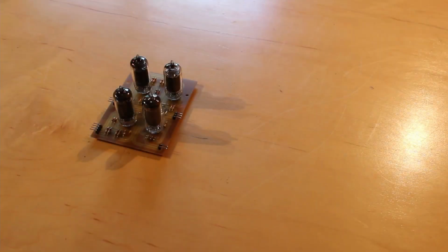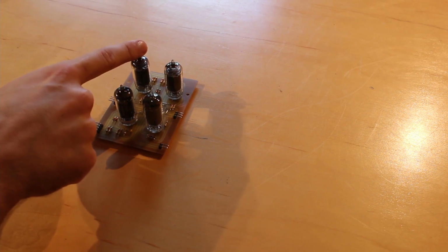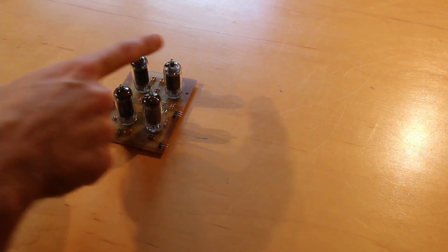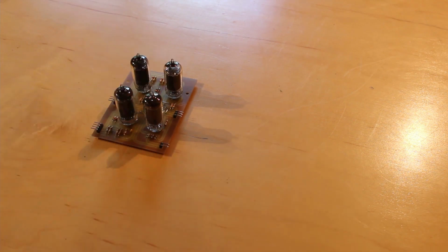Well, this is the board that I want to test out, and it has a NAND gate here for our clock input, a NAND gate here for the IE in output that goes into an inverter, and then we buffer it. So these are those 3 gates that I was talking about earlier. And so I really want to test these out. But just testing them out like this doesn't really let me know if they're going to work correctly with the input enable register in place. So we need to get the input enable register in here as well.